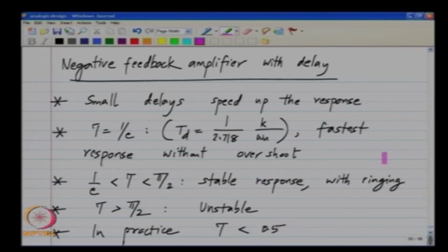What we will do today is to look at how a delay comes about in a real system, because in a real system we will not have an ideal delay as we have been assuming so far. That was just a model for any delay that may come. In a real system, what happens is you will have parasitic poles and zeros in the frequency response at different points of the loop. We will see how they will equivalently contribute to a delay and what to do about it.